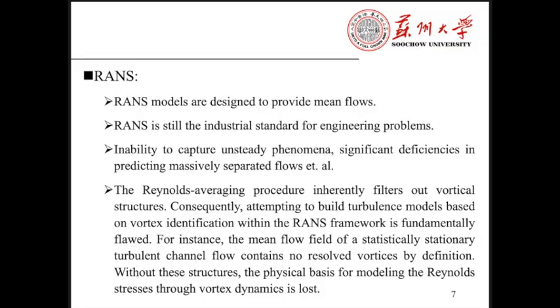For instance, the mean flow field of a statistically stationary turbulent channel flow contains no resolved vortices by definition. Without these structures, the physical basis for modeling the Reynolds stresses through vortex dynamics is lost.